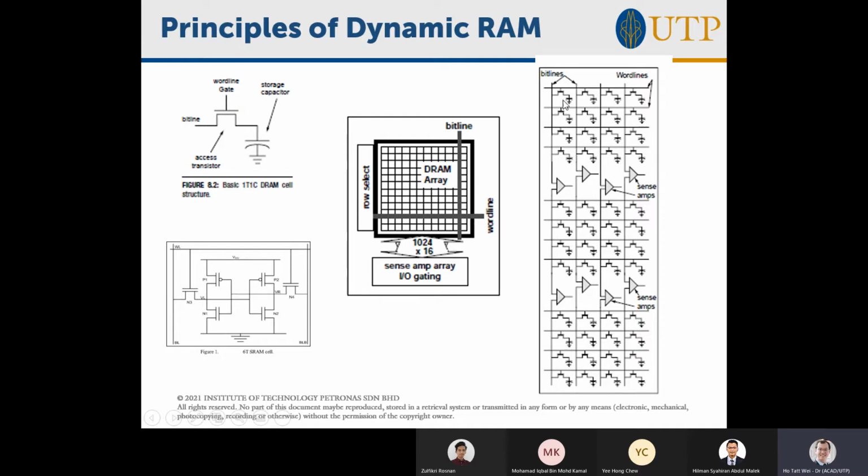You turn on this line, or this line, or this line, or this line. You got it? So this one output here can choose between these bits. And the way I choose which of these 4 bits is I select which of these lines to turn on. Logic 1, right? Because logic 1 will pass this. Logic 0, it won't pass. It's like an off switch. You got that? Yes. So what actually happens is I get a bunch of these outputs here, okay?